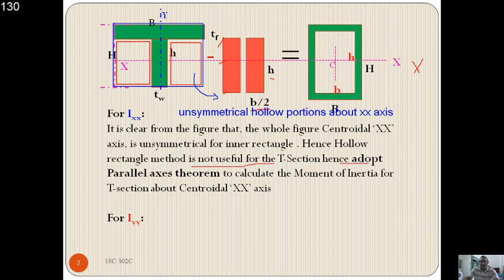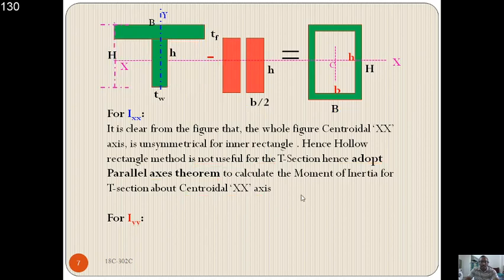So, adopt the parallel axis theorem to solve Ixx and get the centroidal equations. Hence, employ the parallel axis theorem for the Ixx determination. So, we require y1, y2 and y bar to solve Ixx.